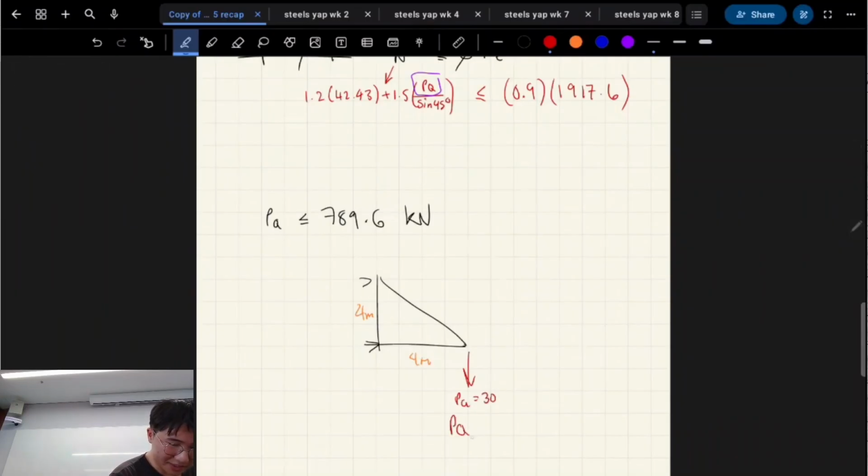If you're saying that PQ is 790 or something in that magnitude, you're like, wait a minute, that can't be right. I've surely got a wrong number, right? The thing is, our section is quite thick, right? So double PFCs and double EAs, there's actually quite a lot of meat on that, right?